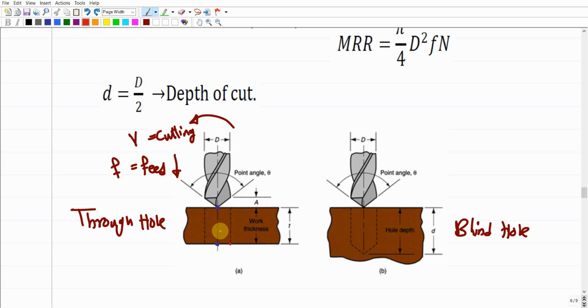So just let me represent this a little bit differently, so it will be clear for you that the twisted drill will be moved down up to here, let's say, and we're going to have this triangular tip. Assuming that this extra distance is the over travel distance, it is going to be about 1 millimeter, for example, 2 millimeters, up to at maximum 5 millimeters. The same thing we would add here in the beginning, some approach distance. This approach distance also would be 1 millimeter up to 5 millimeters.